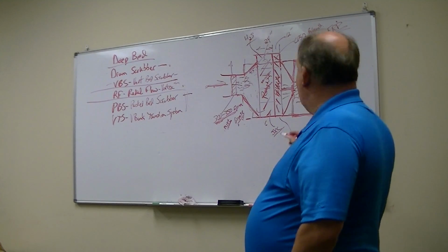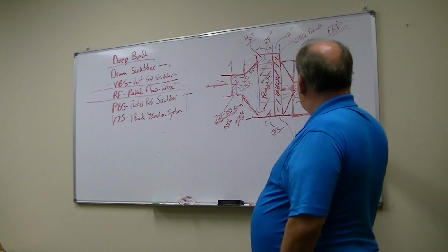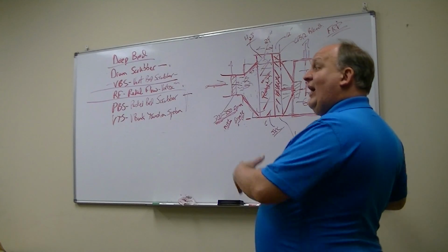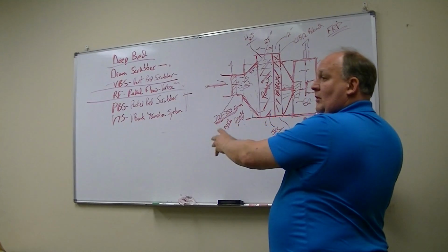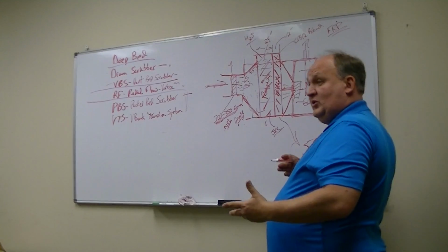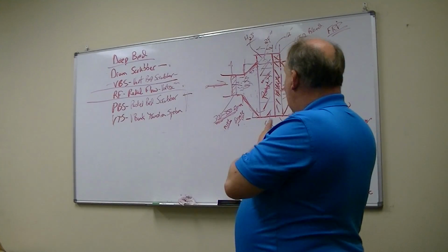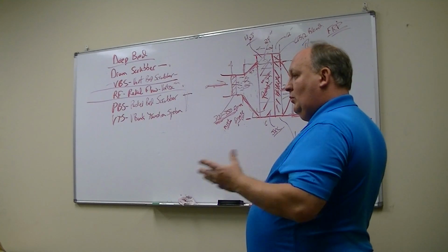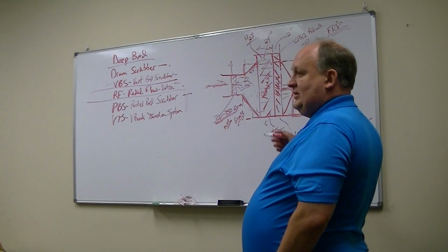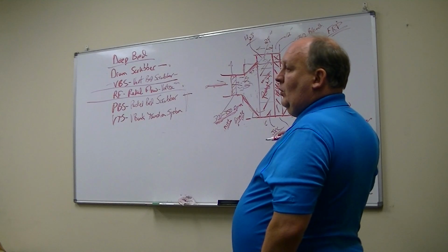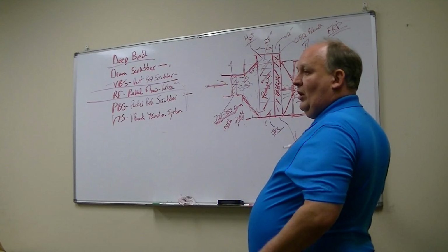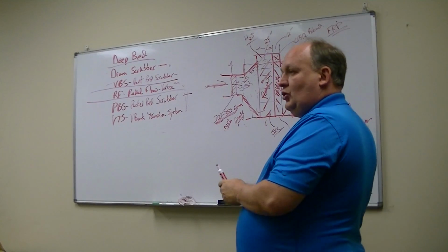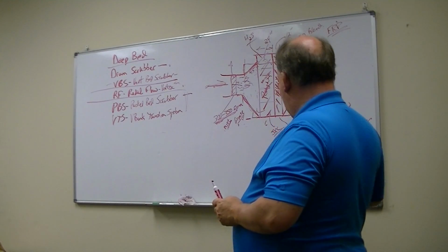Now, one of the disadvantages is that the whole unit has to be bigger to allow for this plenum section, so the fiberglass housing is now more expensive. So there's a little bit of a trade-off. The sales guys are typically going to be working on the design up front, and then they're going to be deciding whether we want an internal plenum fan or external.